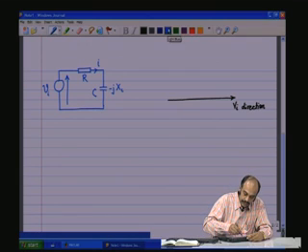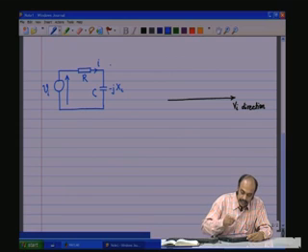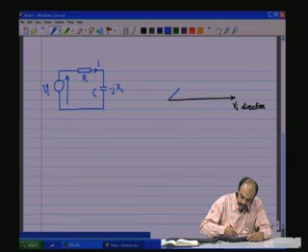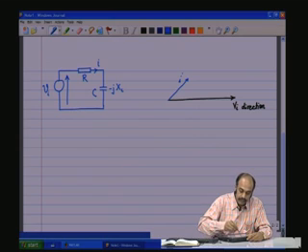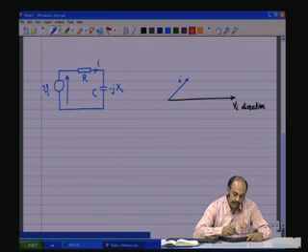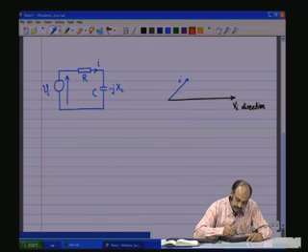And here we see that the current is leading the voltage and therefore, we have the current I. Now, the voltage which is in phase, that is which is I into R, is going to be along the current vector. So, this is going to be I R.